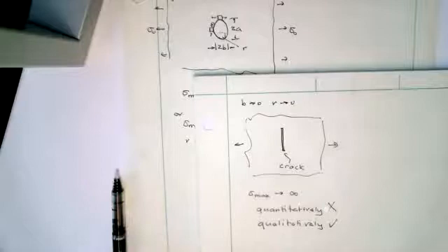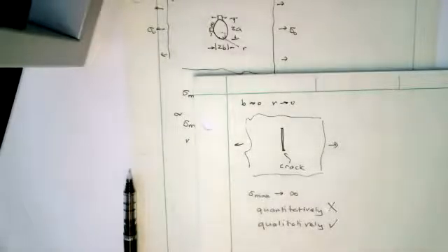I think I sort of demonstrated this to you in the first class. There is a definite stress concentrator of the crack. Here's a piece of paper, and I'm going to pull it on the bottom part here. Now it's got a crack coming down, just meeting the top edge. So there is no question there's a high stress there, but it's not infinite. Okay, it did take a load.